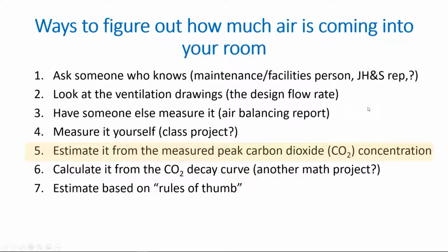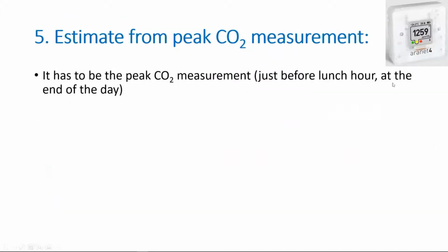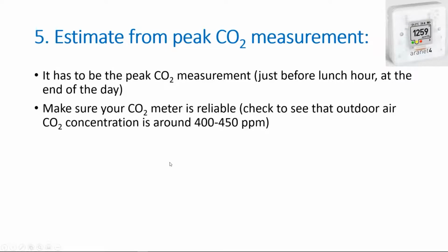If you have a carbon dioxide meter, you can also measure the carbon dioxide and estimate what the airflow rate is. Now, it's best to measure it not first thing in the morning when people are just coming in, but just before lunch hour or at the end of the day when you get your peak CO2 readings. So you want to make sure your carbon dioxide meter is reliable, so you want to check with the manual. It may give you some ideas on how to calibrate it.